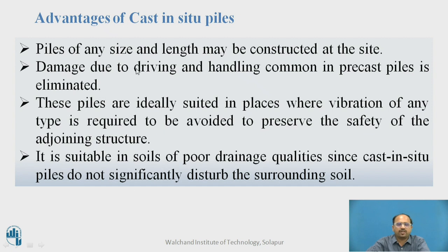Advantages of cast in situ pile: piles of any size and length may be constructed at the site. Damage due to driving and handling, common in precast piles, is eliminated. These piles are ideally suited where vibration of any type is to be avoided, to preserve the safety of adjoining structures. It is suitable in soil of poor drainage quality.